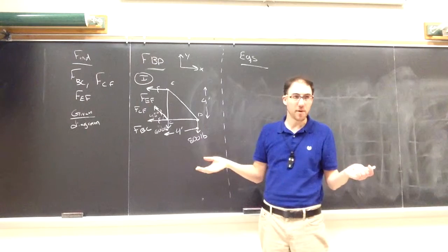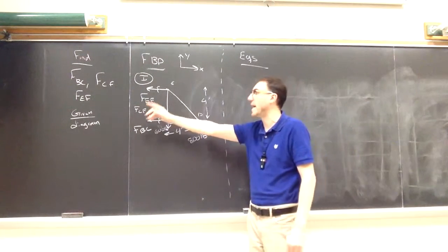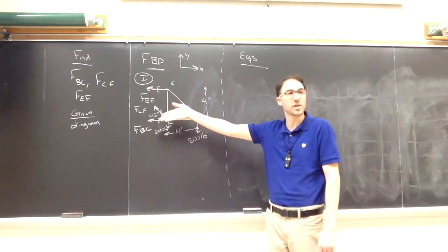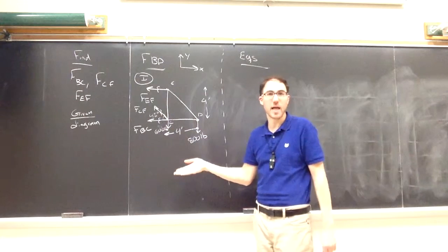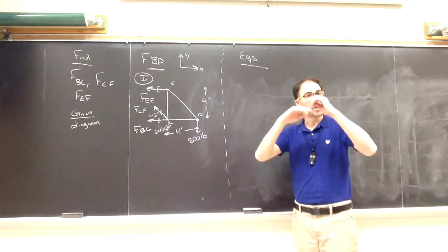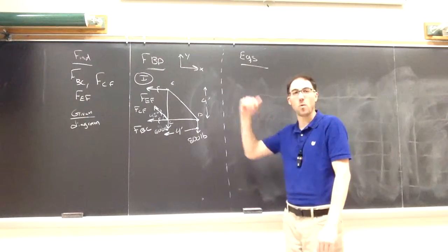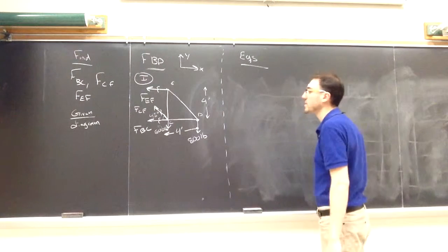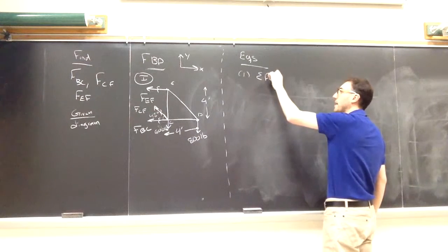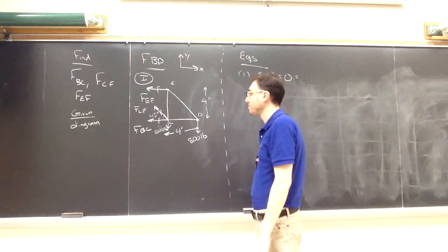The worst place to start, only in terms of the order of doing things, would be sum of forces x, since three of them are going to have components in the x direction. So actually, sum of forces x, I'll choose to do last. But I want to keep reiterating, the order really doesn't matter. As long as you have the equations you need, you could decide later in what order you want to solve them. But since we're doing this by hand, I'll start with sum of forces y in my picture of my sectioned free body diagram.